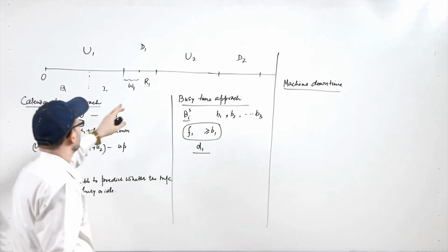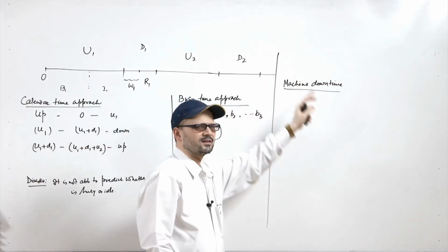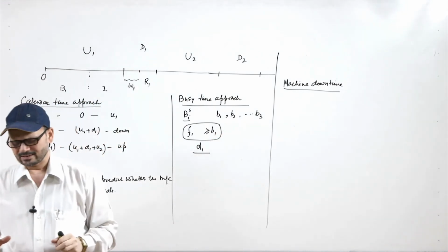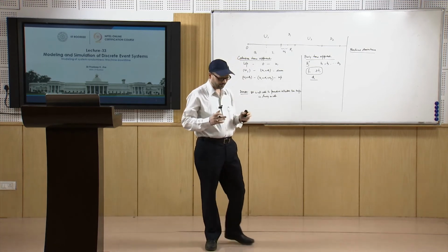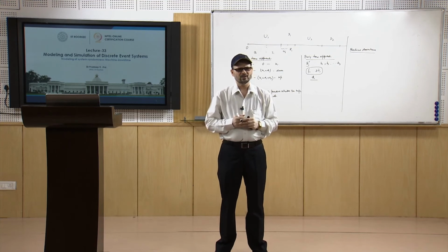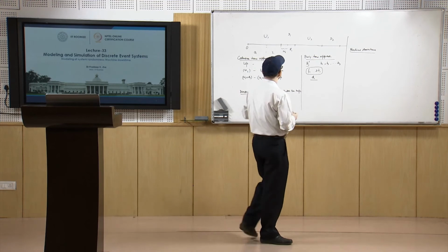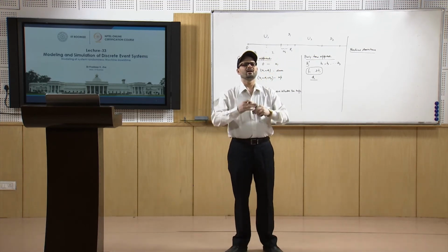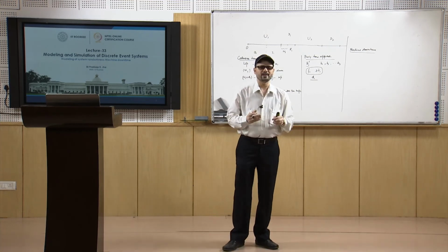And if not, once you have those values, then you can just put in these downtimes. Now, for these uptimes or downtimes, you have different types of distribution functions, and what we see is that normally the gamma function well describes the times at which the machine is going to fail.